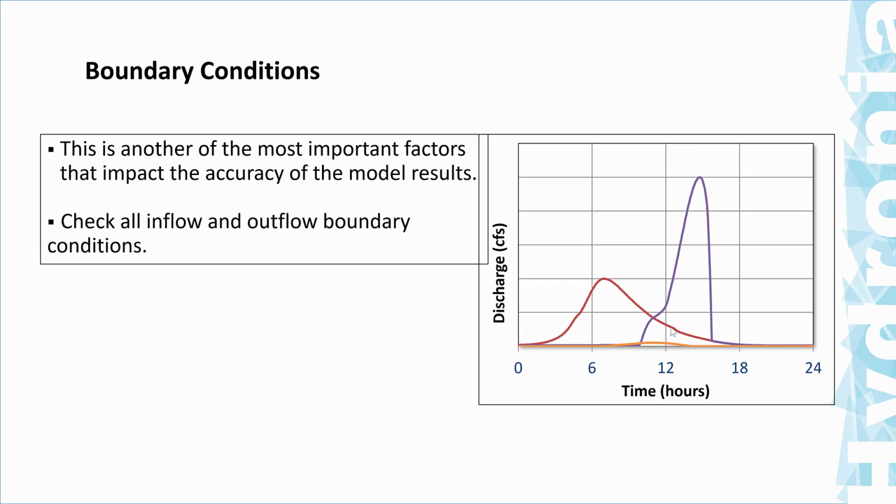Now, remember that you can also, as we will see, use the model as a hydrologic model, where you would not need a boundary condition like this per se, because you would generate a runoff that will end up generating its own discharge. So we'll have to keep this in mind.